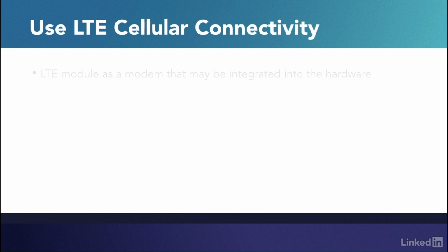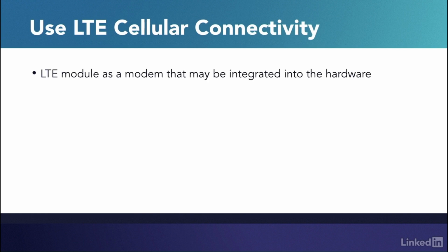For each streetlight, suppose we have a controller IoT board, including an LTE modem connected to our main processor as a peripheral through the serial UART interface, which can send and receive wireless signals from its antenna. And the light is controlled through the relay module connected to the GPIO port. Our OS-based application needs to do some tasks here. For example, operating the modem with AT commands, sending on or off signals to control the light, as well as interacting with a remote cloud endpoint through an end-to-end connection.